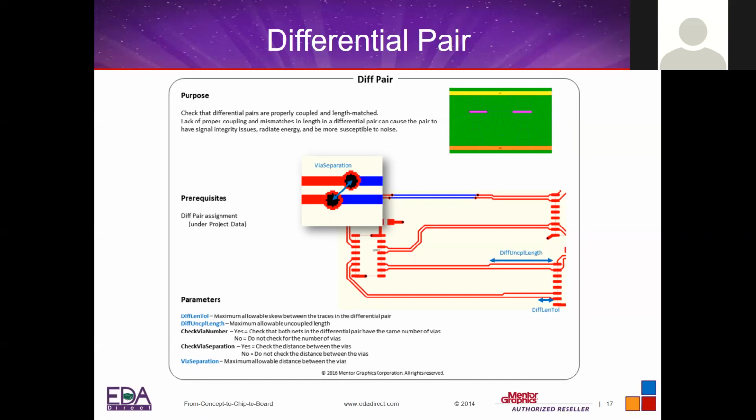And if this was to be a high fidelity speaker, that difference in trace length might cause a phase shift in the audio at the end. So just a simple example. I mean, in real life, the difference might be a lot smaller, but things like that should be checked and should be consistent, and those are good design practice.